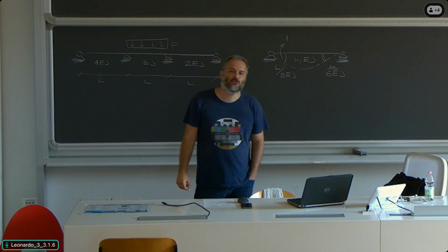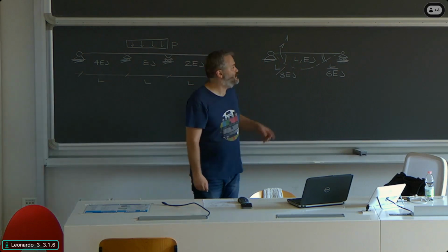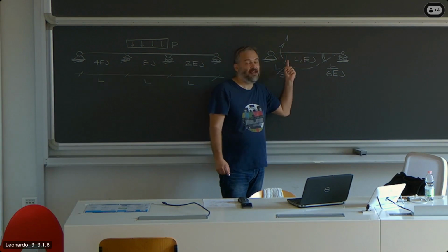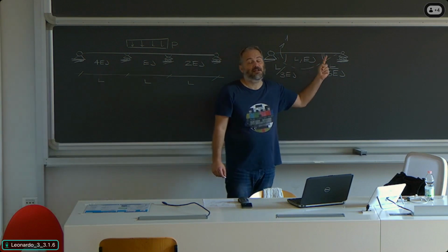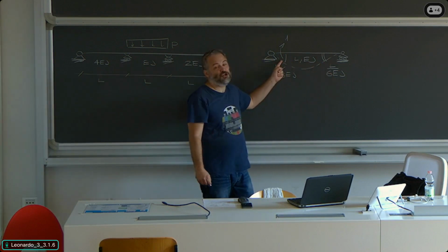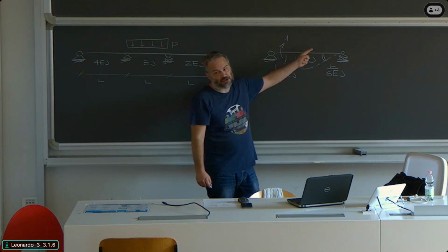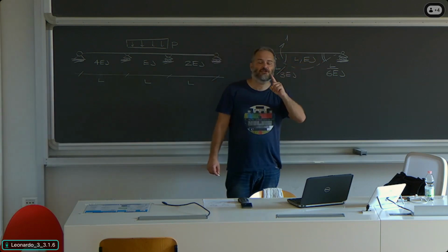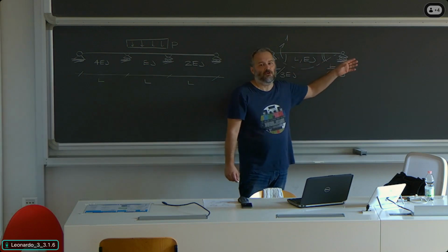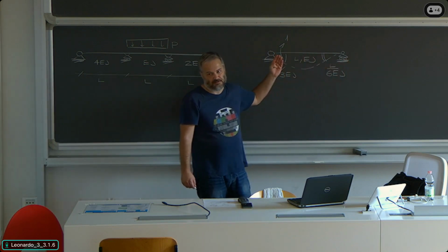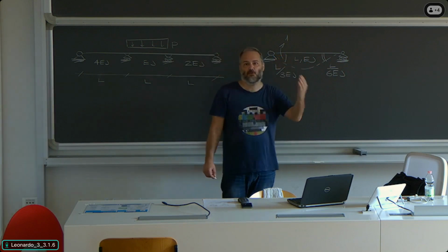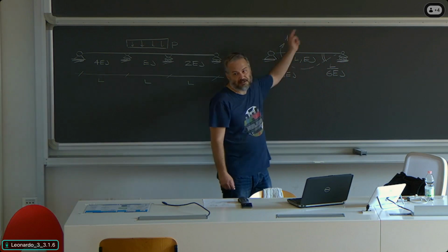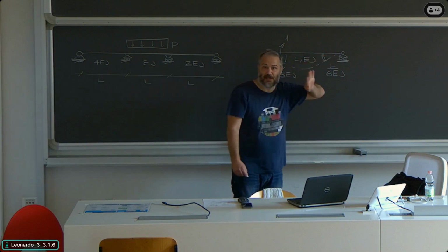Note that when you look at this structural scheme, you shouldn't look at it as moment at the left, rotation at the left and rotation at the right. You should instead consider this is the rotation where the moment is applied, and this is the rotation where the moment is not applied. So loaded end, unloaded end. Left and right do not play a role. What plays a role is where the moment is. Okay? Basically, and this is a question I get a lot during the written exams, you can use this coefficient also if the moment is applied at the other end. Okay? Just to make things clear.